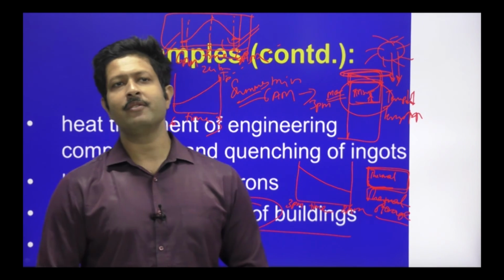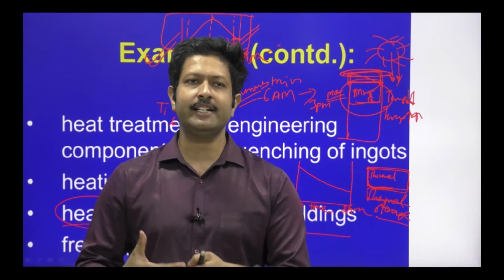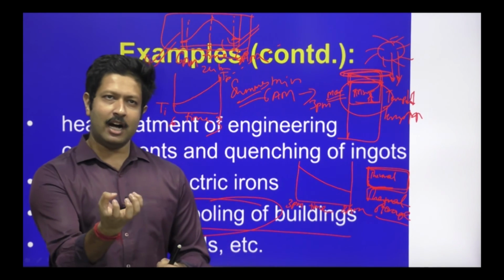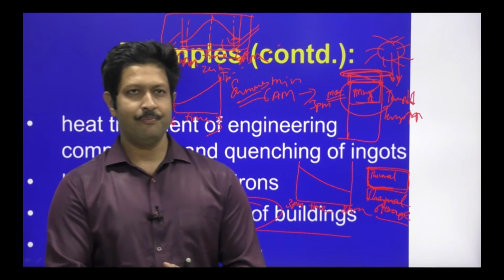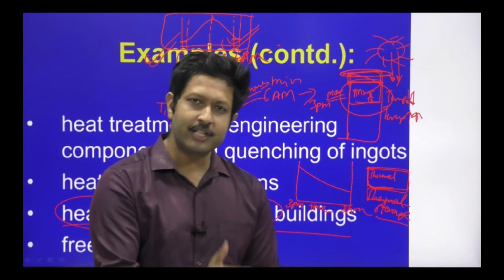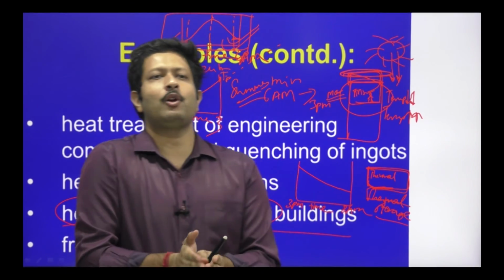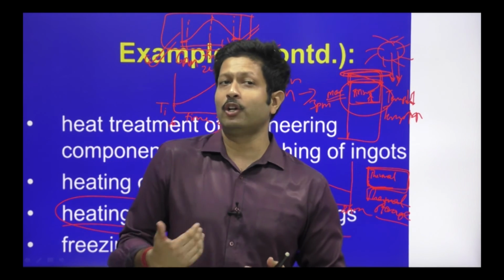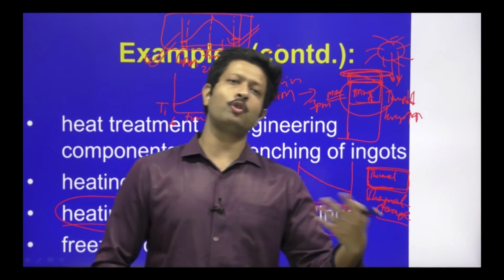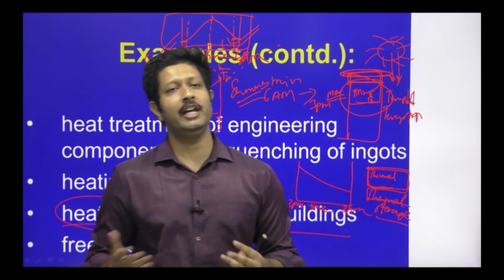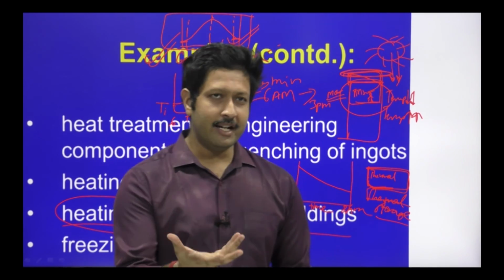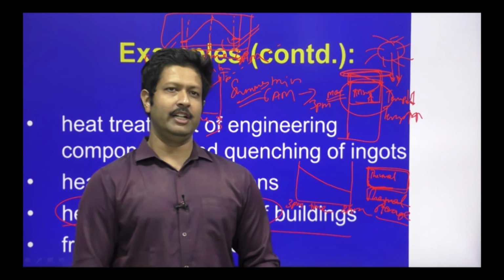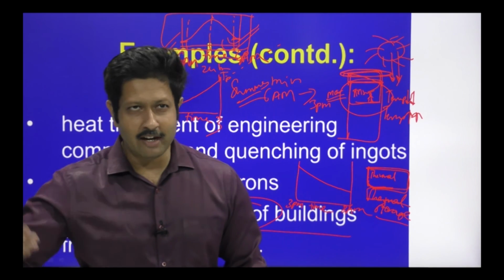So what happens is, since during the night time there was no heat, the cooler temperatures are actually stored in the thermal storage. It takes near about 6 to 8 hours to release that particular temperature which is colder. So in the morning you actually feel colder, while outside the temperatures are increasing. Whereas this concrete and this brick is taking in the heat from the peak daytime and further onwards.